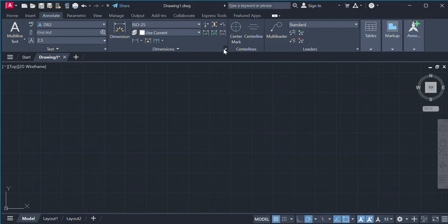Then now you're gonna come to your dimensions drop down menu, and if you remember what we did, you are gonna create a new one. Then you can also call it drawing 2. Then start with, say, annotative. Click on the annotative as well, and you use it for all dimensions. Because it's easy to say, no, we'll just need linear or angular dimensions or radius, but essentially you want peace of mind, so set it for all dimensions, then say continue.